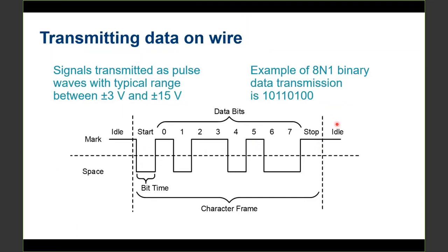One thing I just want to put out there, another thing that goes against intuition, is that this digital 1 is actually, if you hooked up an oscilloscope to it, a negative voltage. So if this graph is here, this is actually a negative voltage going up this way and a positive voltage going down this way. So a 1 would be considered this negative voltage, and the 0 would be considered positive voltage, or the space.